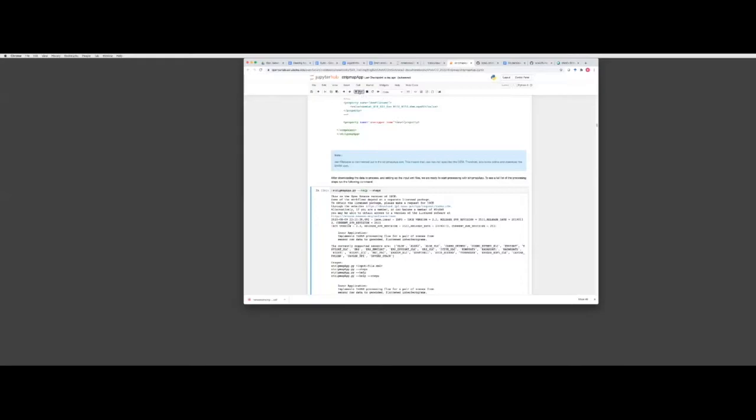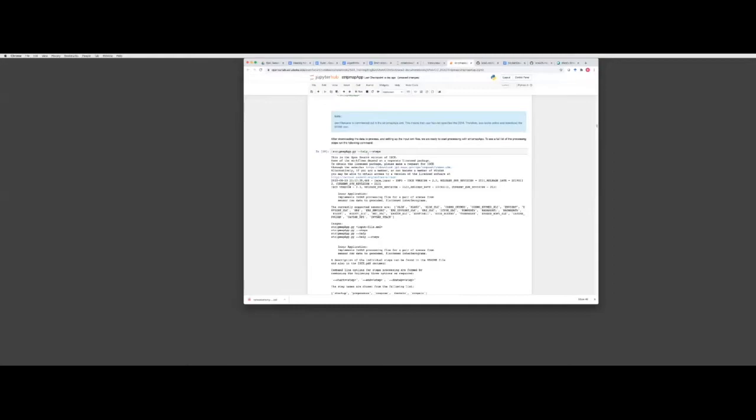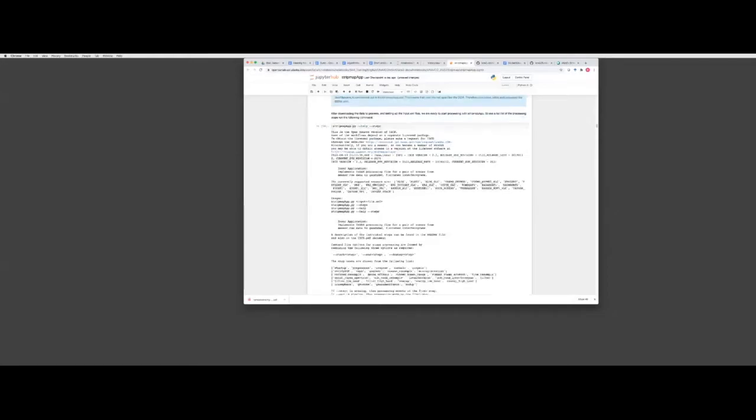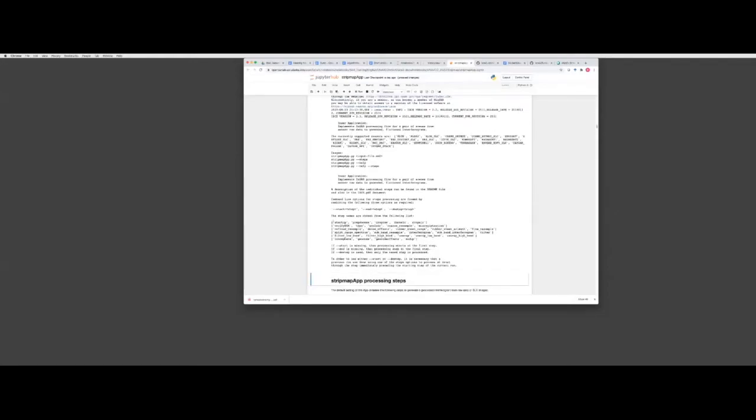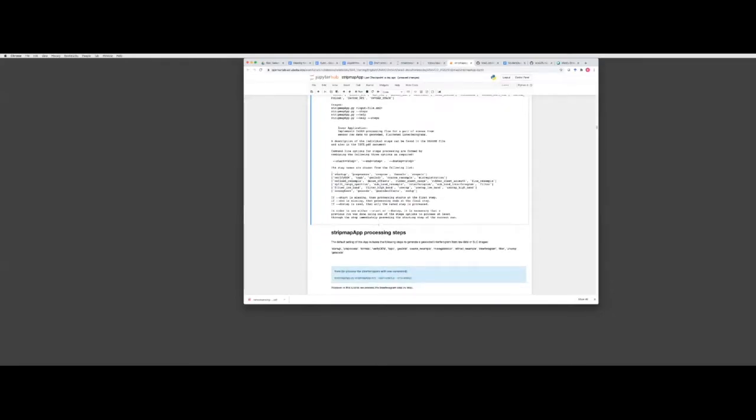So we can go ahead and take a look at first, before starting to run the different steps. Let's see what steps we have. If you just say stripmapApp.py --help --steps, then you see a help description with different steps. The first step is startup, preprocess, crop raw. We will go through each step one by one, but it will give you a general overview of the different steps that we are going to go through.